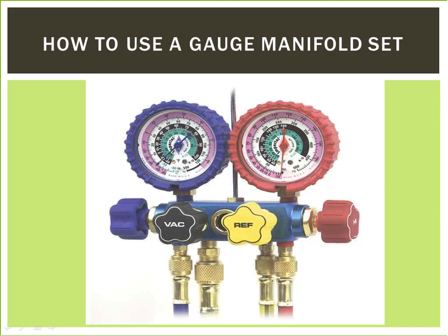Open the blue low pressure valve and then the red high pressure valve on the test gauge's manifold, bleeding only the air from the hoses. Close the valves as soon as a refrigerant appears. Take the readings on the gauges and compare to the readings specified in the AC unit's service manual.